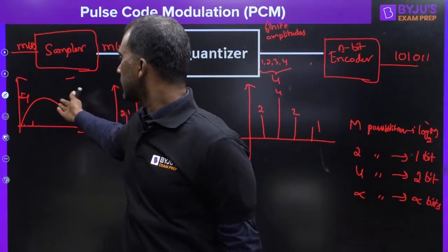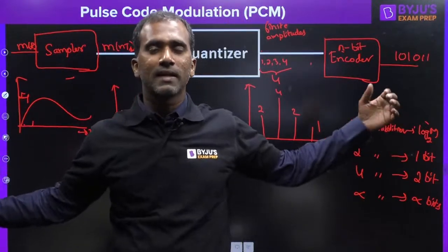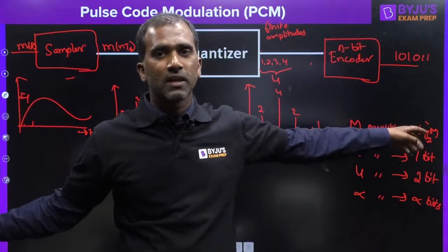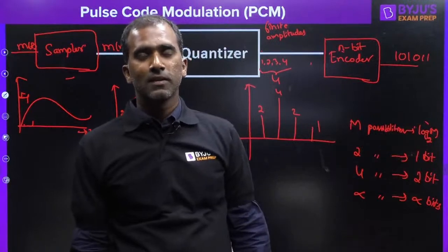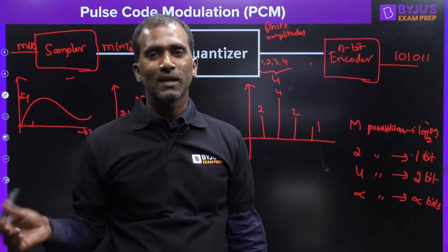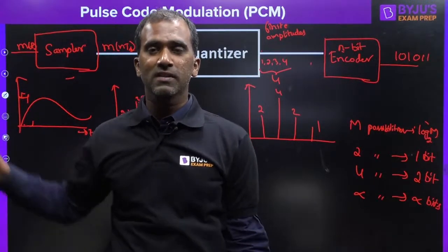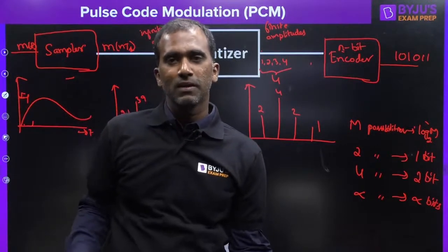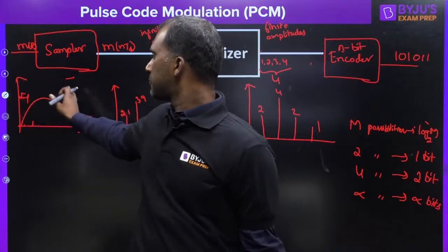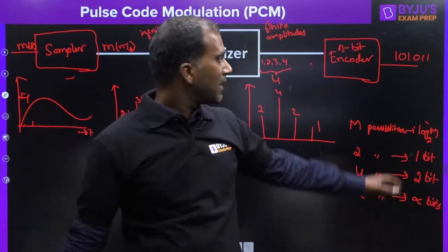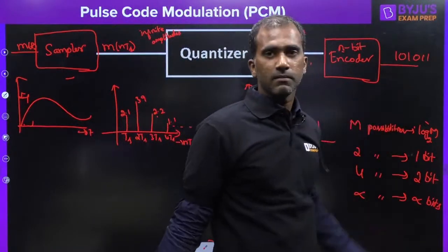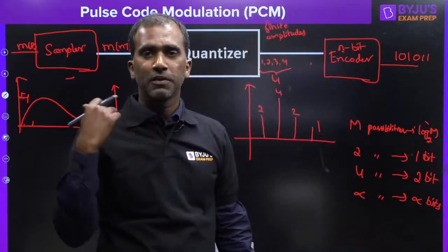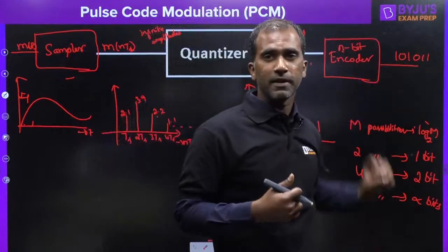For a simple signal, if you are using 8 bits, you'll get some rate x. Instead of 8 bits, if you are using 80 bits, instead of rate x, you are getting 10x rate. Which means instead of sending x data, you are trying to send 10x data for conveying the same information, which is useless. Say I've spoken here for 1 minute, you have recorded it, converted it into bits, and you got 1 MB of data with 8 bits.